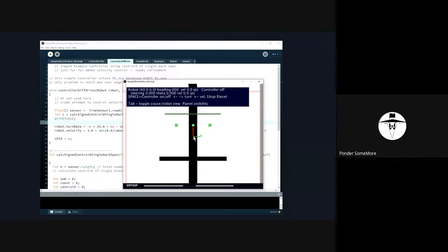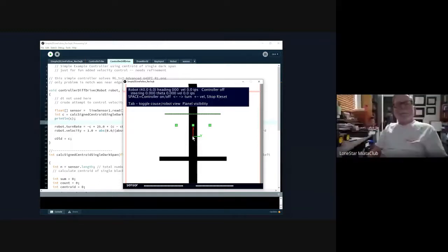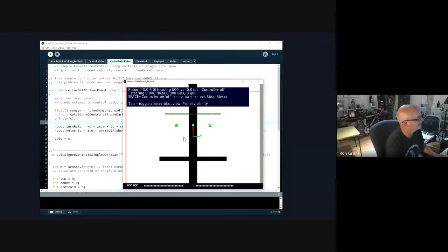Yeah, and if you factor in real world lag, like reaction time from your PID controller to the actual motors and all that kind of stuff, your zero point is actually forward of the physical center point of the axle. So yeah, with infinitely fast update and sensing, you could move this very, very close, but maybe you'd have a singularity if it's right at it.